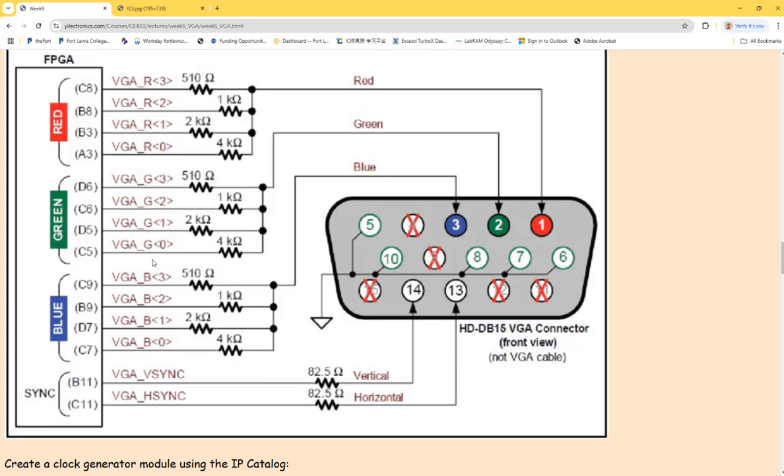That is why a lot of times you should know that superposition is one of the most important theories you have learned in circuits. A lot of people don't even have an assignment in the Circuit 1 class for that theory. It's most often used. You see, inside the controller, before it's delivered to the VGA port, what's happening here? If it's 4 bits, and we know that the MSB takes more weight, the MSB of the 4-bit data must contribute a higher analog voltage. And this is the superposition theory here.